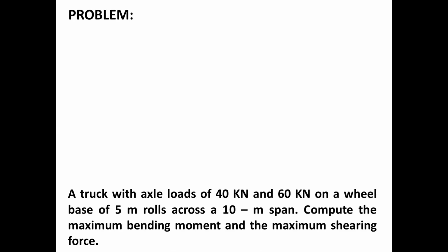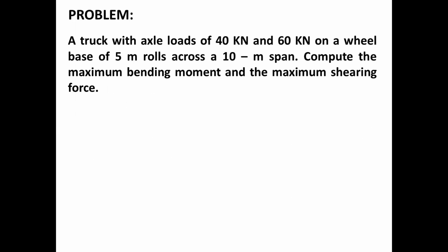Now, let us try to have a sample problem para mas maintindihan natin ang ibig ipahiwatig ng definition ng moving loads. A truck with axle loads of 40 kilonewtons and 60 kilonewtons on a wheelbase of 5 meters rolls across a 10-meter span. Compute the maximum bending moment and the maximum shearing force.